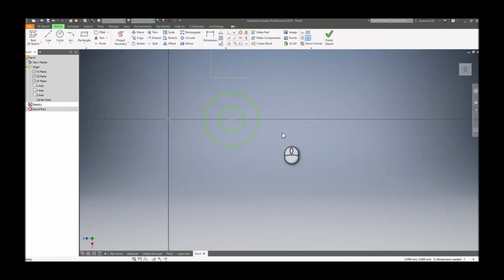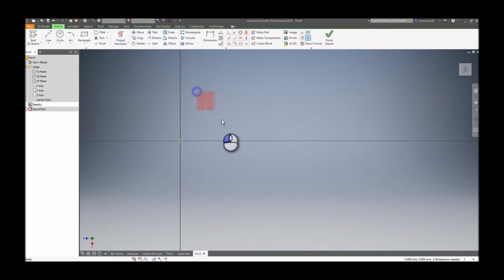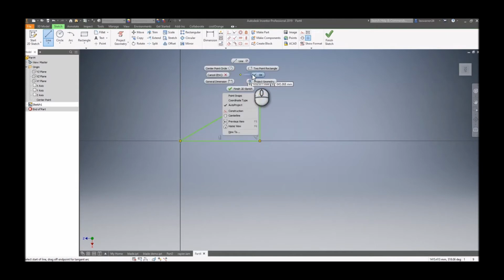And as we move across, we now actually have the constraints, which make sure that when everything's green, it's unconstrained. When it's purple, it's fully constrained, so you can't give it any leeway. So if you see here, as I go right angle, it goes into a perpendicular constraint. But now, let's go through. So you've got